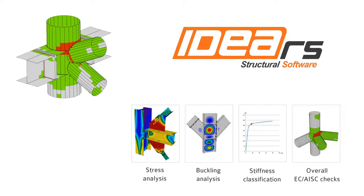CBFEM allows total freedom in the geometry of the connection, on the contrary with the traditional component method that has a lot of restrictions in the type of connections that we can design. For example, connections with hollow sections.